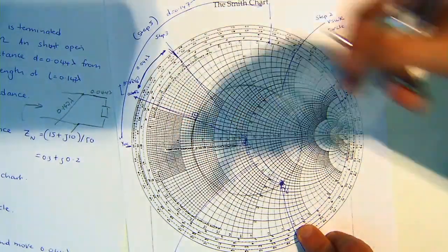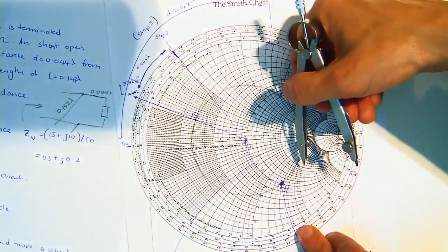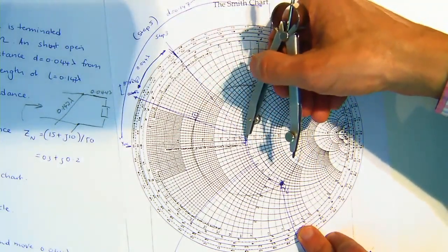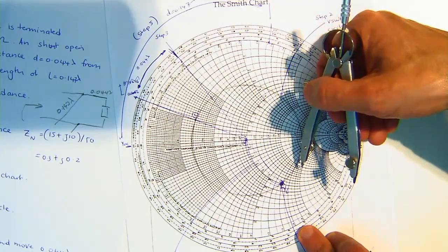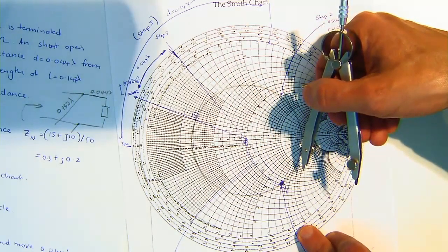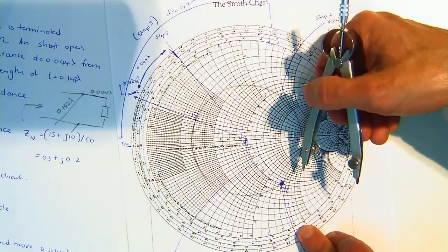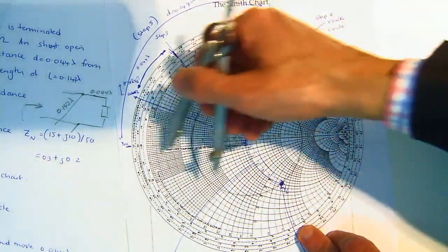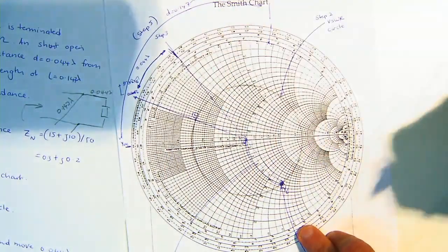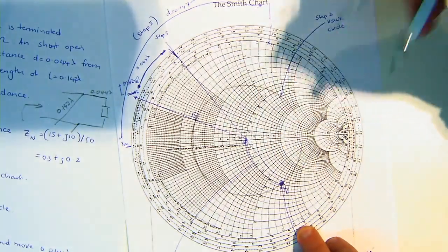You just flip through the centre of the Smith chart, the 1, 0 point, until you hit the opposite line. Should it be negative 1.6? Yes. Yes. Negative 1.6. Did I say positive? I'm sorry. Below this line it's negative, above is positive. Thank you. Yes. Okay. All right.